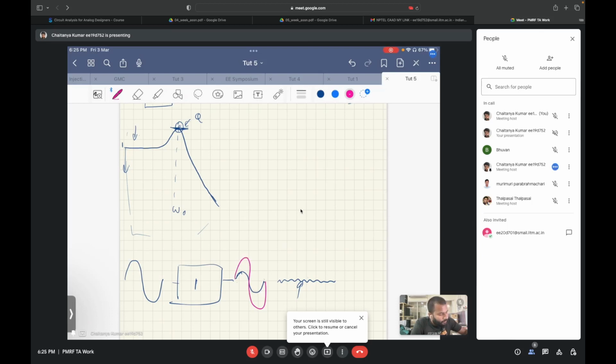Now if the gain is less than 1, which is the case if you put a high quality factor biquad initially, you will get a sinusoid that is attenuated, and the noise of the second biquad will affect it more. Do you get my point?